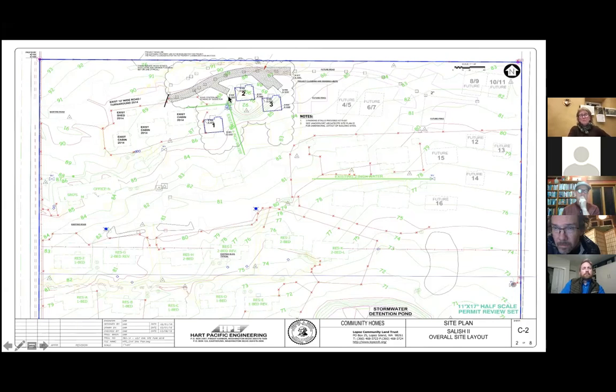And again, this ties back into stormwater. There are rules that say, if the land has been planted in trees for 2 years before you start your next development, you can simply count this area, right? You can see this outline right here as your area of development.